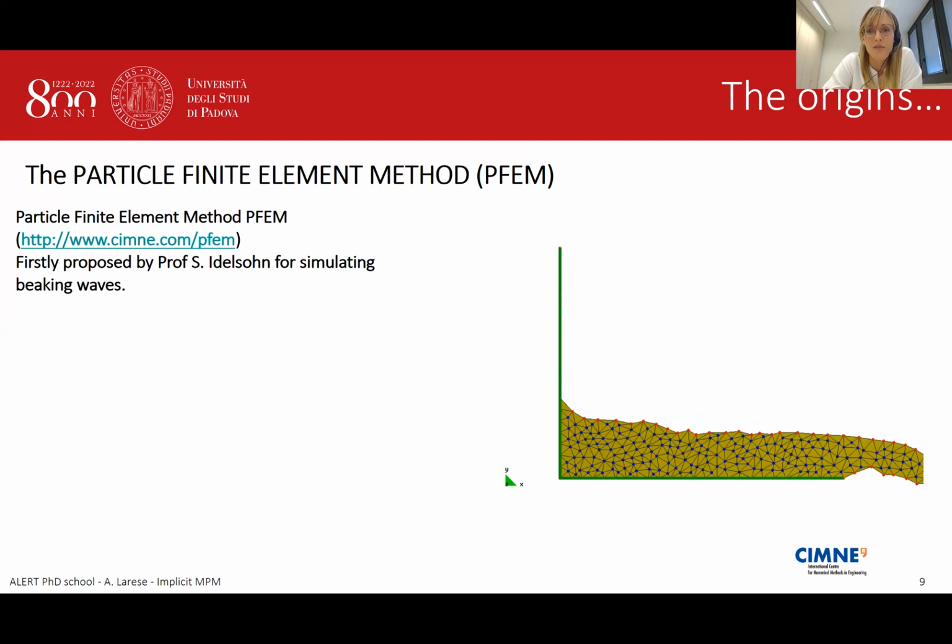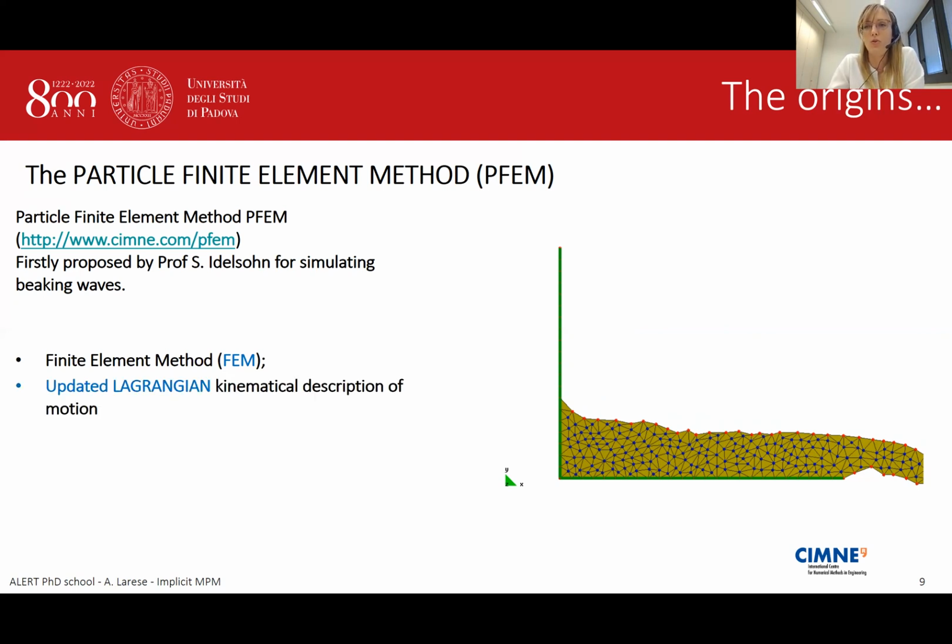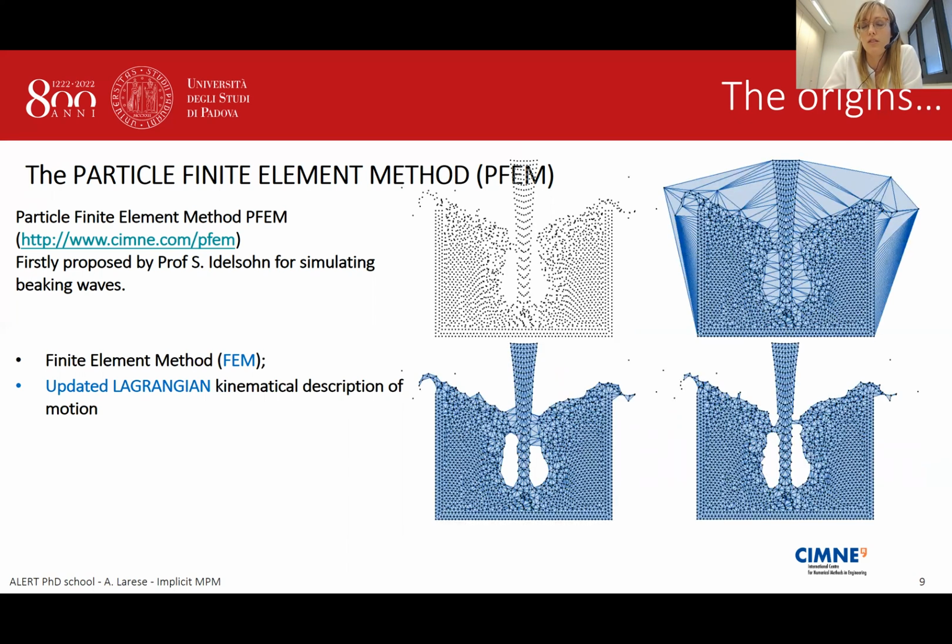So I started working with particle methods, but calling them particle methods is a little bit misleading, because what is PFEM? It's finite elements. It's Lagrangian finite elements. So you are meshing your material domain at every time step, solving your equation in a Lagrangian kinematic framework. And at every time step, since the mesh is highly deformed, especially in CFD, less so in structural mechanics, what you need to do is to erase the mesh completely, keep the cloud of nodes, and then reconstruct the mesh.